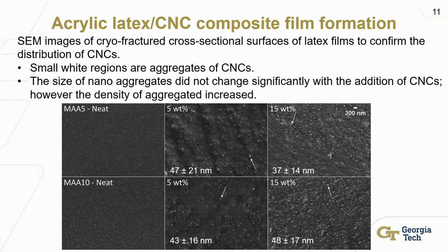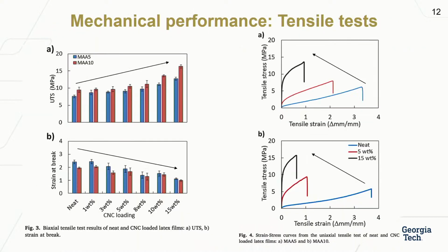And so at this stage, we have a nice film-forming latex binder that is pretty close to a commercial composition that has no volatile organic compounds in it. So the next question then becomes, well, what's the minimum film temperature at which it can form a film? We found that was about 0 Celsius, so even at close to the freezing point of water, this can still form a film. The next question is, what are the mechanical properties? Did we actually increase the modulus? Did we actually increase the hardness?